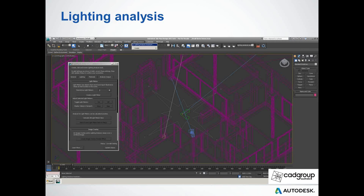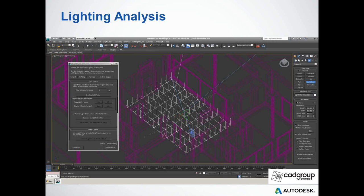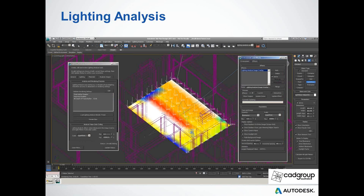One of the tools that you might not be familiar with is the daylighting analysis tool. This is an American LEED accredited lighting tool that allows you to link your Revit model into a 3ds Max Design environment and set up a number of light meters to be able to record the daylight illuminance coming into that space. So what we have here is a plane at each intersection of those arrows. It records illuminance and gives you a numerical output and a pseudo color overlay.